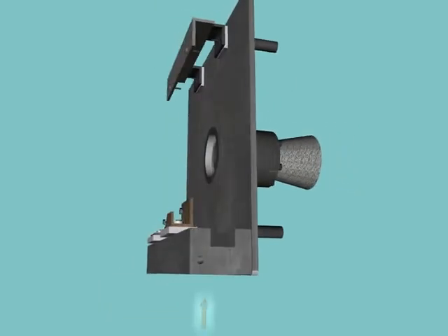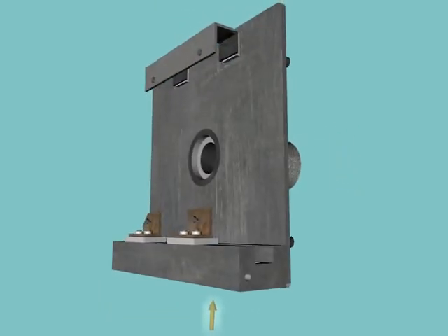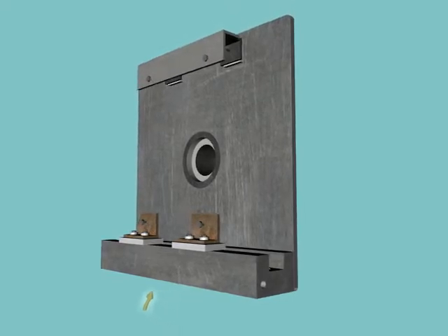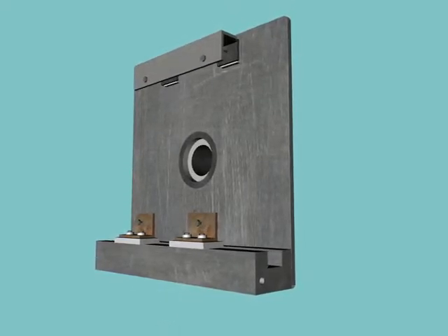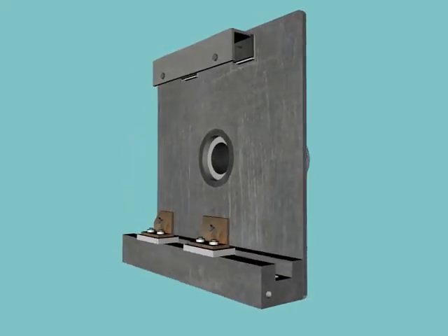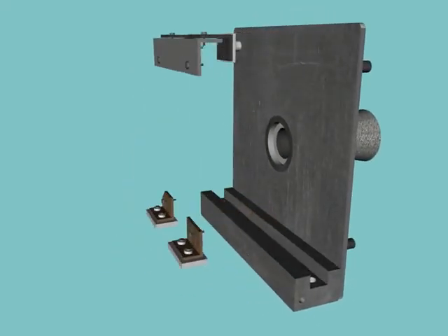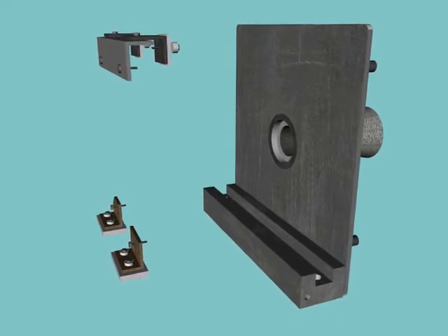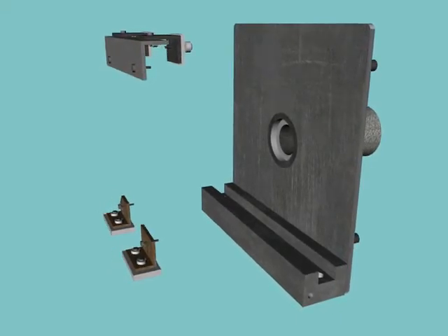The thruster's base is made out of stainless steel and is also at anode potential. The connection to the anode's line is on the side of the thruster's base. The connectors between the anode and cathode plates are electrically insulated and so electrically floating.